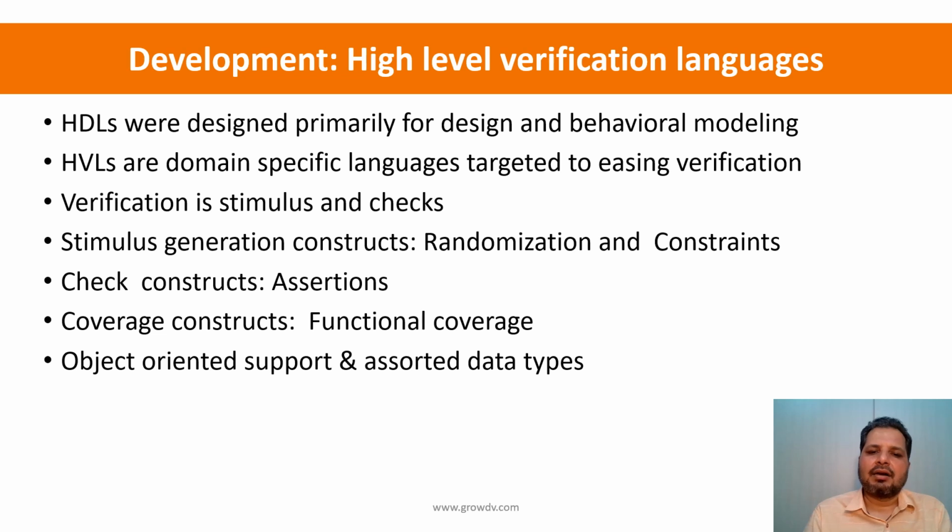And then there is a construct called assertions, and assertions is an area by itself. Assertions are useful for both the dynamic simulation world as well as for formal verification. Formal verification heavily relies on assertions. Assertions are also hard to pick up, but if you pick them up, that will be useful for both dynamic simulation as well as formal verification. Assertions are very useful when you want to do either interface level or DUT based white box type of checks. Any signal level checks you can do very well using assertions.